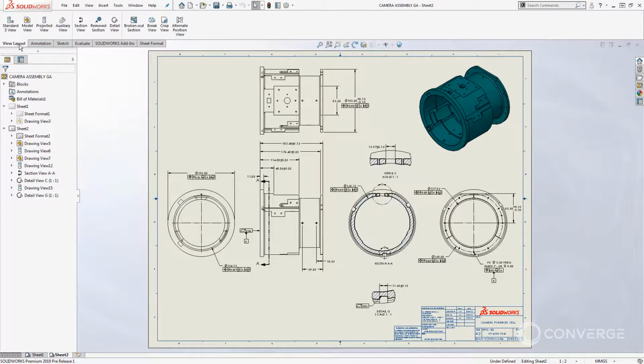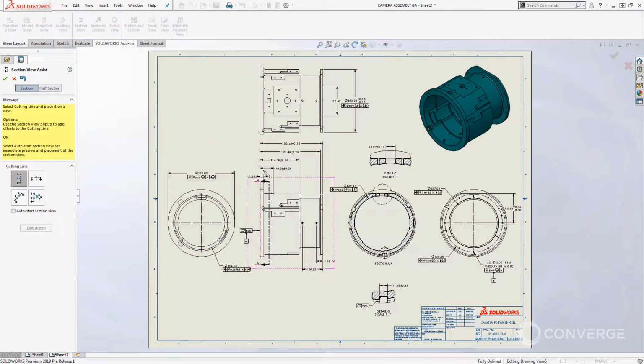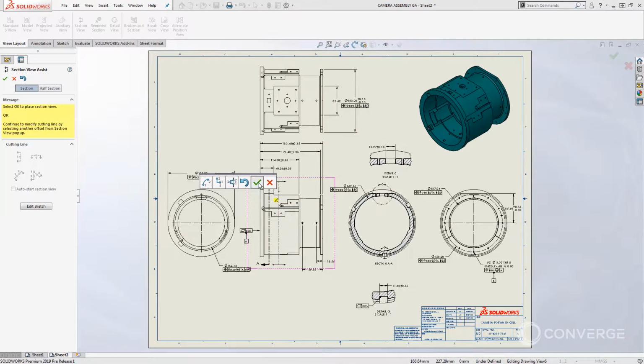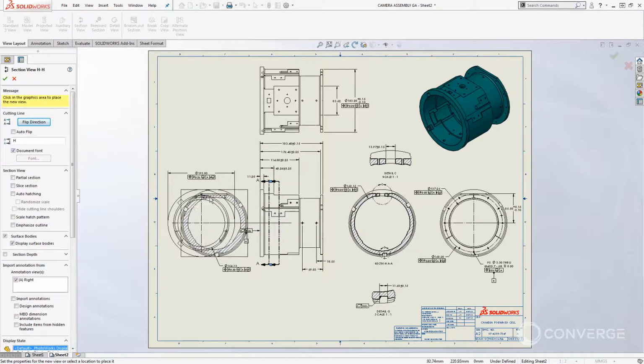The first update I want to mention is something called removed section. If you create a section view on your model, this section view is going to create some construction geometry, and you're simply going to be able to drag your view out left and right. And if you need just a small slice of this, you need to work on section depths and creating exactly what you need in terms of slicing that section.